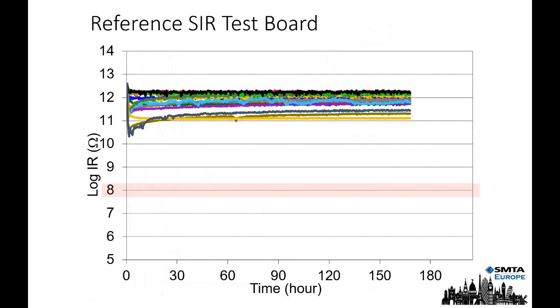But please, one word of warning, if you're ever using SIR testing, always look at the samples. And quite often I've worked with companies that look at the data but don't look at the samples. So you can have a pass and you can have a failure, but it's looking at where they fail. That's the most important thing. So if you're ever doing testing with a laboratory, make sure you look at the sample parts as well as the data together. For those of you who are familiar with this test, you'll know that that's obvious, but please look at 2 sides, because those 2 sides tell sometimes a slightly different story.